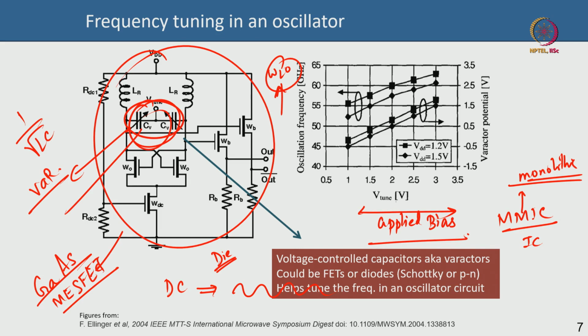in a wafer. Essentially all resistors, capacitors, oscillators, mixers, frequency synthesizers, what have you, everything will be fabricated along in the same process flow along with the active transistors or diodes or whatever on a particular wafer. You are not integrating externally sourced resistors or passive components, you are not integrating anything external. That is called MMIC. It makes your chip very compact, very small, and it is a very good form factor that people like.